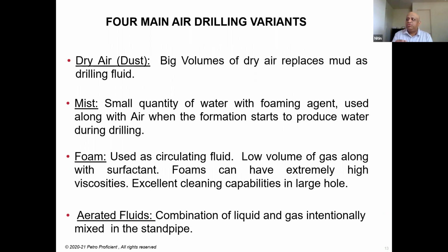So most of the time when you go to any well site for air drilling, you would go with all the required combination of options available. For example, you may have to switch to mist drilling while you're drilling because you see that water is produced. So you would basically take mist drilling as the option.